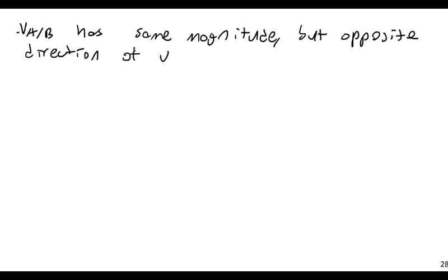So the sense, or the direction of the relative velocity, depends on your choice of reference point. However, the angular rotation is independent. What direction the relative motion is pointing will depend on what reference point you choose.